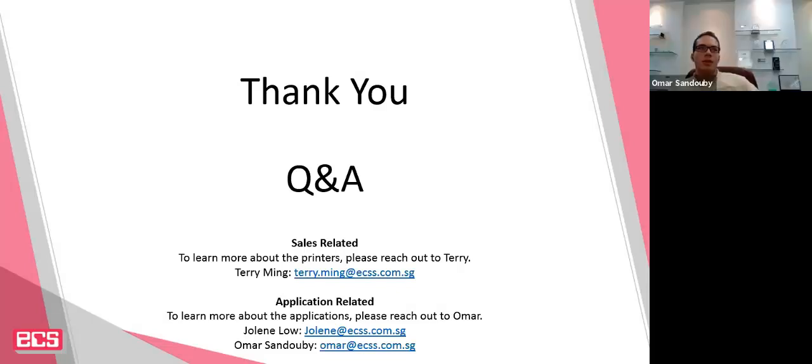Oh, for instance, when we go into casting, if you saw in the video, there were these green wax patterns and some are purple. The wax is different. The support wax is still a wax material, but in casting applications the wax is slightly harder. It has a higher melting point, so you make sure that you dissolve the support wax without dissolving the main build part wax. And it's harder; the melting is also quite different. And I believe that depending on the part that you cast, you would have to make different considerations.